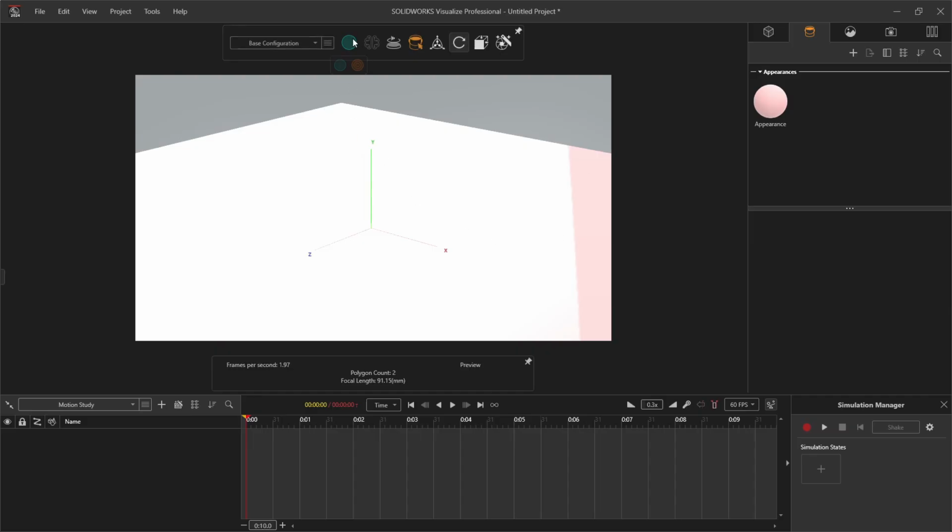Right now the renderer selection is on preview, but to see the appearances in real view you need to change the view to accurate. This can slow down the software a little if you have a lot going on, so I tend to only use this to get a preview of my appearances or render windows before the final renderings are done.